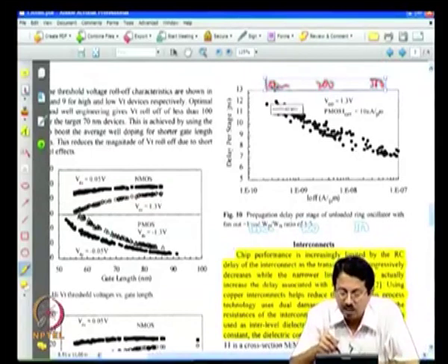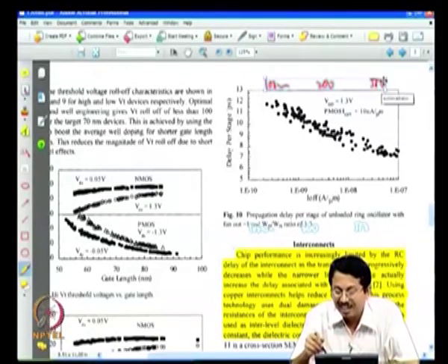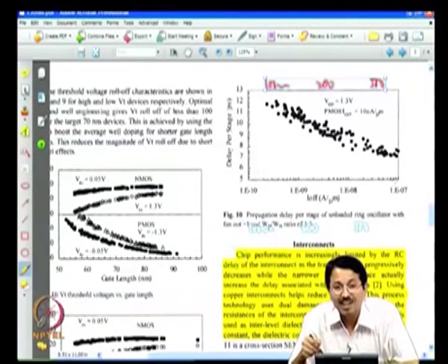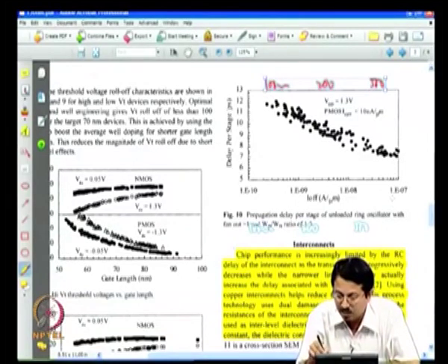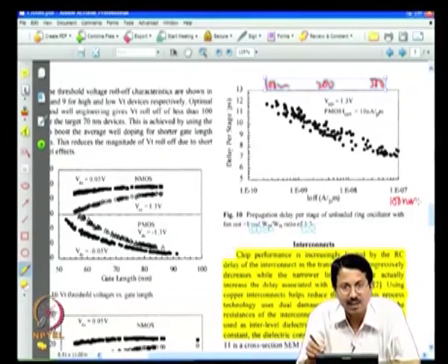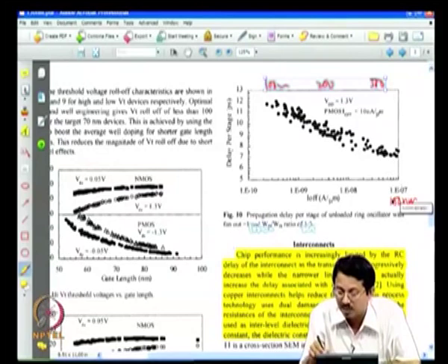Right, 100 nanometer is out here. 100 nanometer also results in large leakage current. Longer channel length results in small leakage current, correct. Let me write it here so that it becomes very clear. So this is a 100 nanometer transistor, let us say 100 or 170 nanometer in this case. They have gone down to 70 nanometer, right. So this would be something like 70 nanometer out here, and this may be 100 nanometer and this may